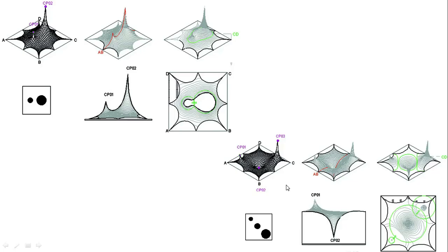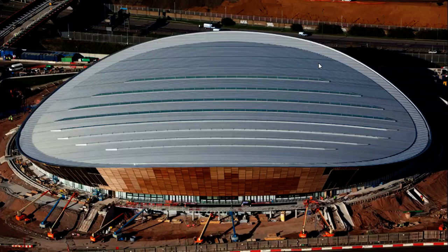Now again, just to remind you, the beauty of these is that on the one hand you're just playing around with geometry, aren't you? But once you've achieved what you want, when you put your compression masts in and you pull, and you put your mass down underground, you are making a workable structural form. And the grid that the geometry has naturally formed is the wire, is the cable net. That is where your cables will land. So the geometry and the structure are working in absolute perfect harmony.